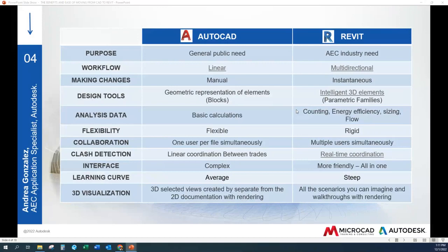Another feature, and this is the only one I mentioned that Revit has that AutoCAD doesn't have, is the collaboration. Revit within BIM allows multiple users to work on the same file simultaneously, while periodically synchronizing all edits to a live central file. The project can be on the same server or even in a different country while users work in a single central model. In AutoCAD, shared views can be created for visualization and doing markups, but it still doesn't allow two people working on a file at the same time.